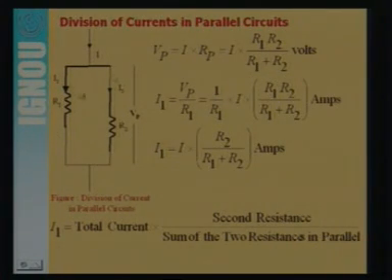So here we can derive this thing. Suppose the equivalent voltage, when we supply the current I through this network of the two resistances R1 and R2 in parallel combination, then we can say the total voltage across this is Vp. Vp is equal to I Rp, where Rp is the equivalent resistance of this. Both are in parallel, so the equivalent resistance is R1 R2 divided by R1 plus R2. You can write it like this.